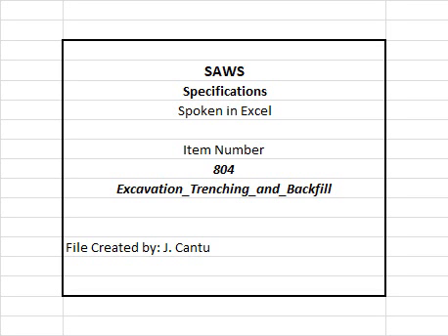6. Potable water and recycle mains backfill. A. Bedding material. 1. The existing material at the bearing level shall be removed and replaced to a minimum depth of 6 inches or 1/8 of the outside diameter of the pipe, whichever is greater, with bedding material. 2. The bedding and initial backfill materials for concrete steel cylinder pipe, CSC, ductile iron pipe, D, wrapped steel, WS, pipe, high-density polyethylene pipe, HDPE, and polyvinyl chloride pipe, PVC, in all nominal diameters shall be composed of well-graded crushed stone or gravel conforming to the requirements of Table 3 unless modified by the engineer in writing.